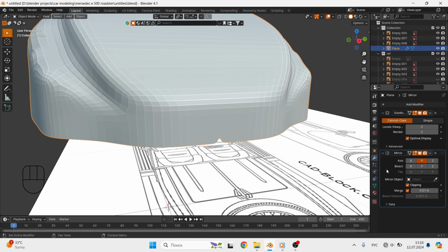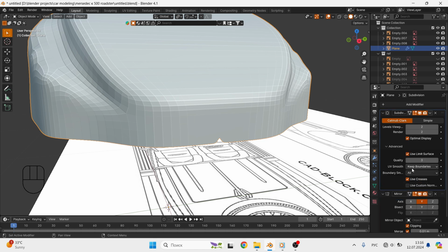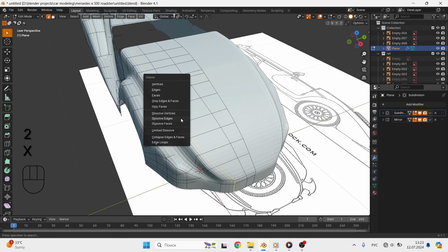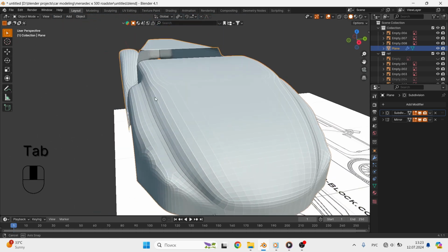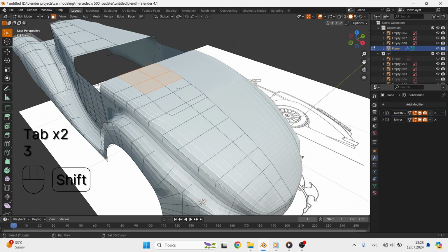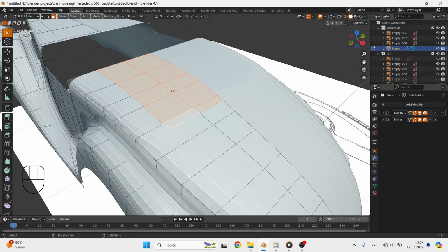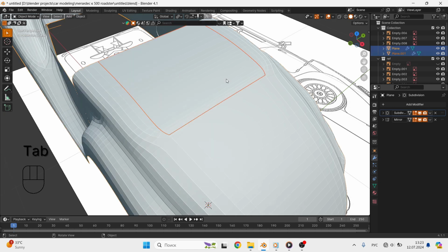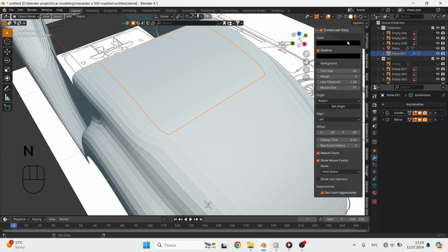Usually, organic models are built from full quads, four-sided polygons. This helps to avoid deformation during the rendering and animation stages. So, the shape does not matter much as long as the number of sides is 4, unlike hard surface modeling. At the same time, the use of n-gons, polygons with 5 sides or more, is not recommended at all.